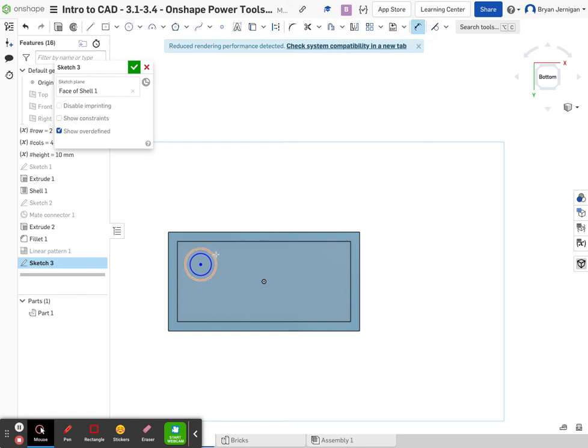The outer circle's diameter is going to be 6.314. The inner circle is going to be 0.75. I'm sorry, the inner circle is going to be 0.75 from the outer circle. So let's go ahead and exit out of here, delete this. Let me redraw my inner circle. My inner circle is going to be 0.75 from the outer circle. It's got to be 0.75 from the outer circle.